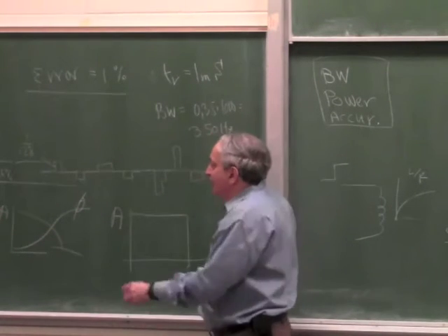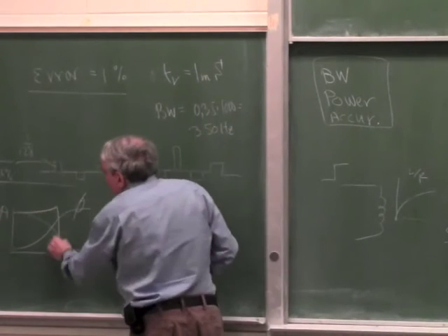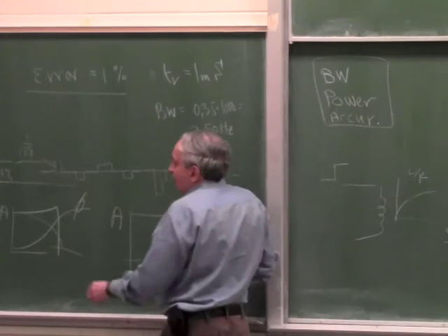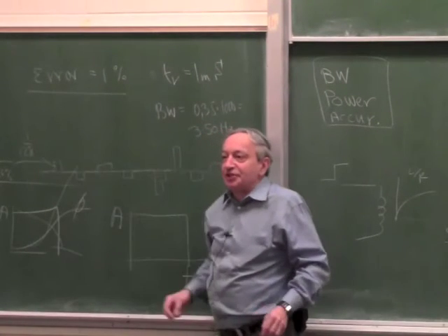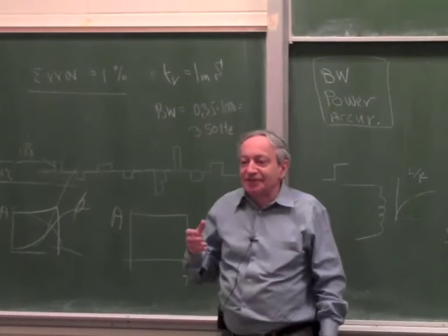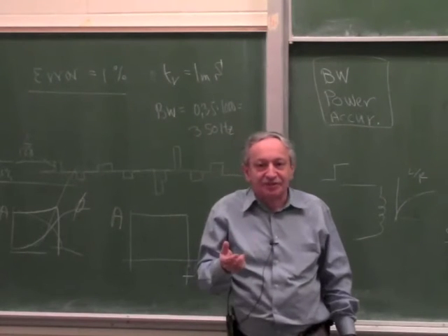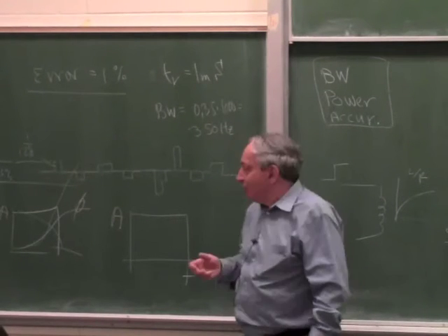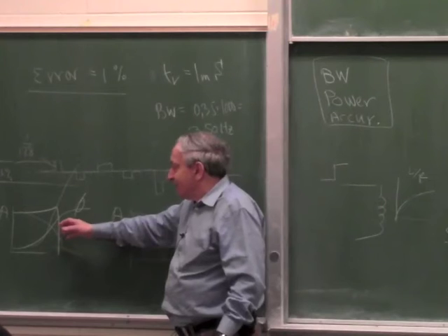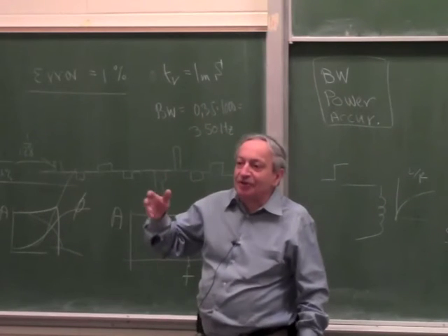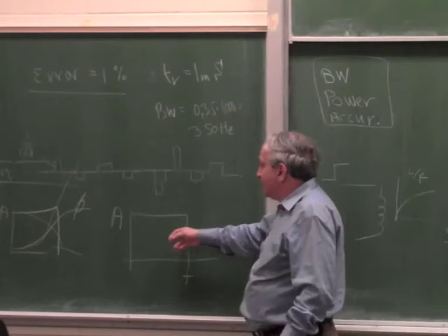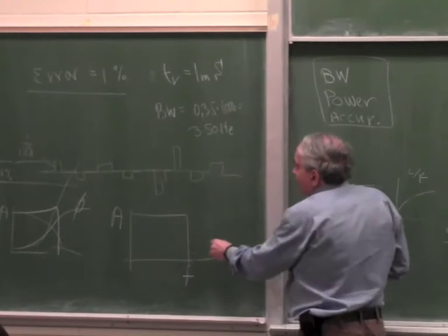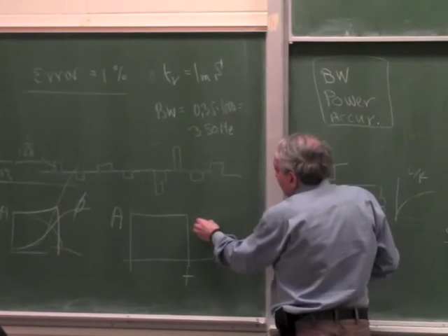Now if you have a very steep amplitude plot, the phase plot is very complex and goes up to a much bigger phase shift. Since a servo is very sensitive to delays, it's very sensitive to phase shifts. So if you want to put in a better filter, the first penalty is it can have very big and complex phase shifts, and the second penalty is it also has ringing, because if you send a pulse through a filter like this, it will come out ringing like crazy.